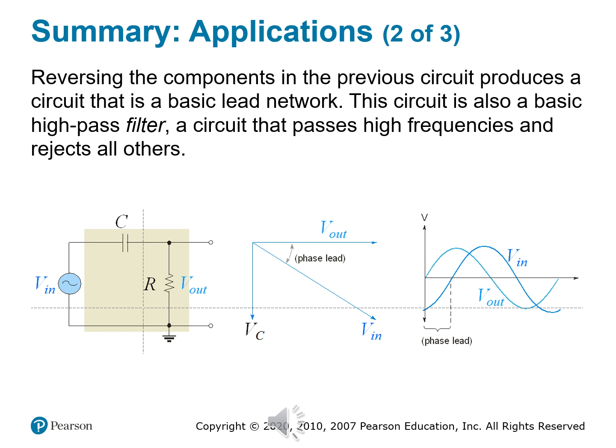So here's the setup. We take our signal V sub in and we run it through a capacitor first, then the resistor to ground. This time we measure the output across the resistor instead of the capacitor. And what's the result? Instead of lagging, the output leads the input. And it's not magic, or is it, right? It's the math of how voltage and current behave with capacitive reactance. Like before, the phasor diagram shows V sub C dragging behind, and that forces V out to jump ahead. This is your classic phase lead.